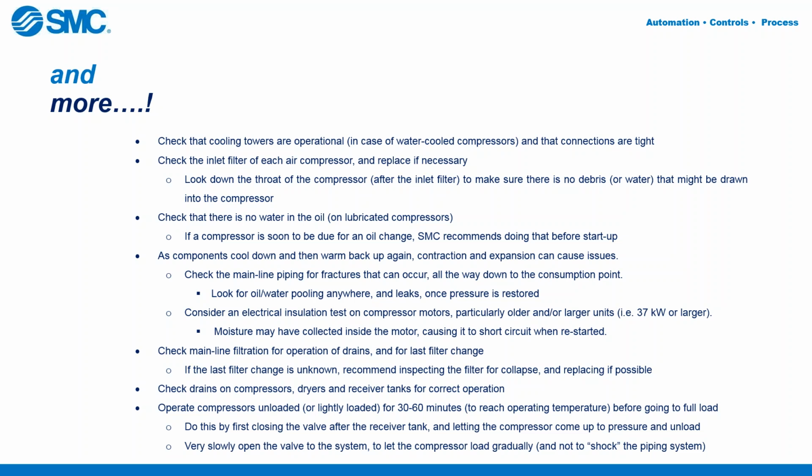We'd want to check that cooling towers are operational, particularly in the case of water-cooled compressors, that we don't start up a compressor without making sure that its cooling system is working correctly and connections are tight. Before starting an air compressor, check that the inlet filter is clean and replace if necessary. Look down the throat of the compressor after the inlet filter. Make sure there's no debris or any water that might have leaked in over time.